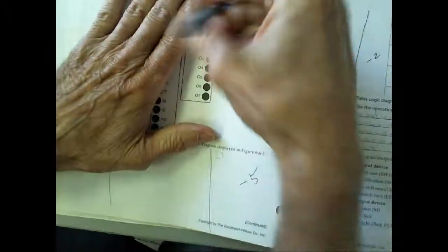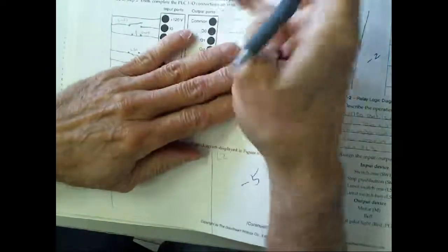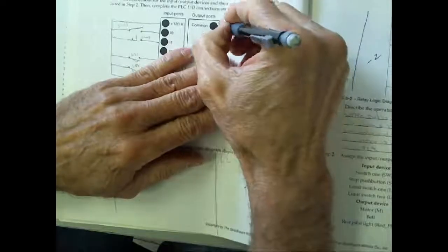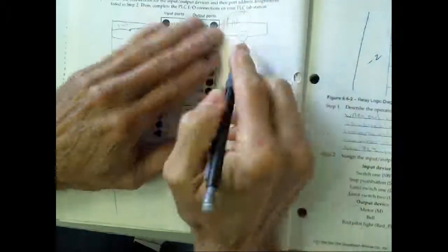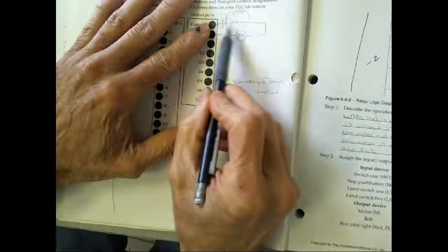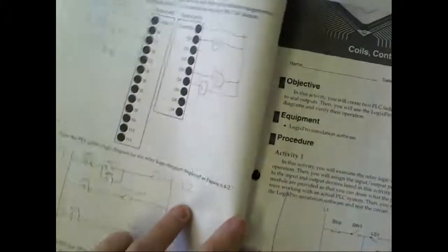So normally this is where we would put our E-stops. Not on our input. We would normally put our electrical E-stop there, and you can see what it does. It removes the power from all your outputs. Now, if I needed to figure out what to do in a PLC circuit, then of course that's about the only place we would use that examine if open.